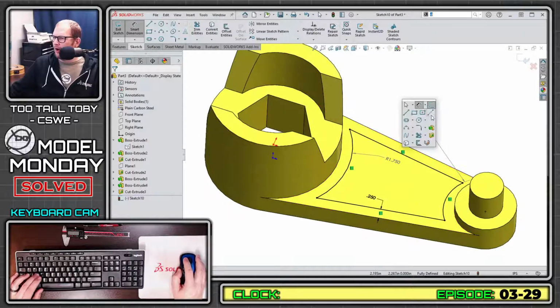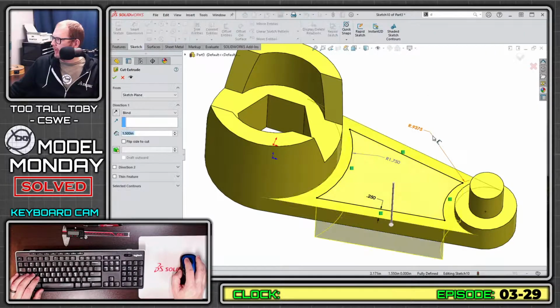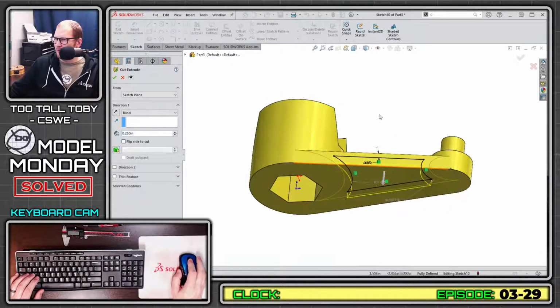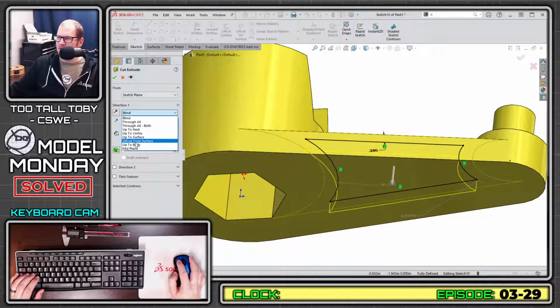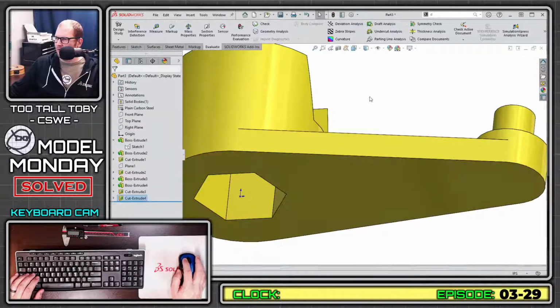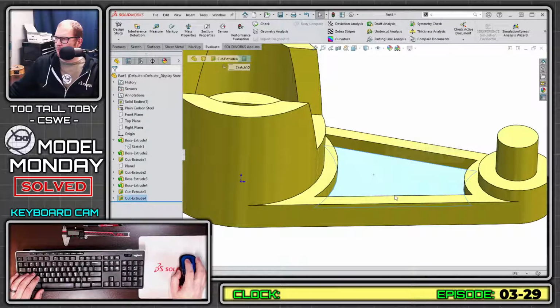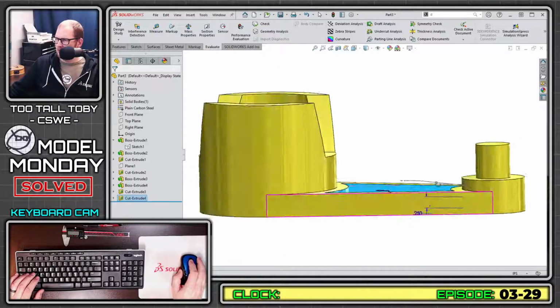And then for our pocket, this is going to be S key extrude cut, and it looks like it is offset from surface 0.25, which again, I know that's half of that distance, but just to match the customer's expectation, we'll make it offset from this surface so that our 0.25 dimension is going there, just like what the print's showing.